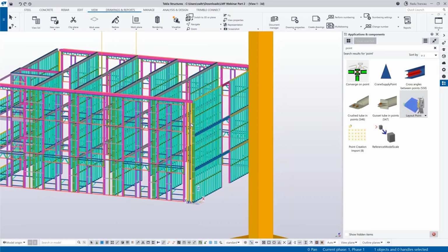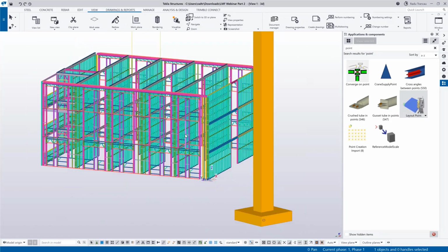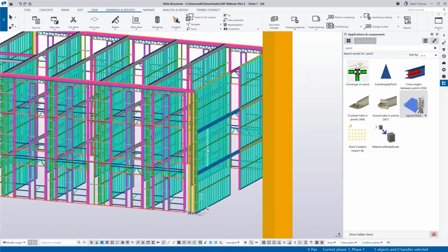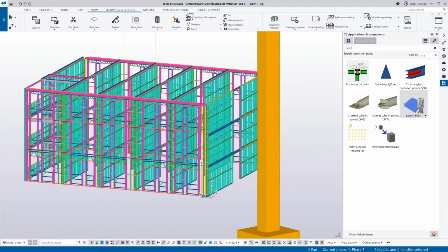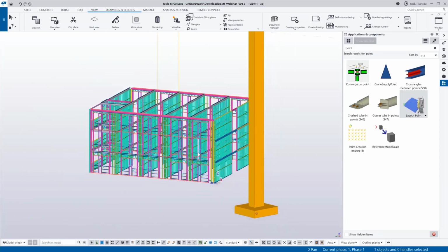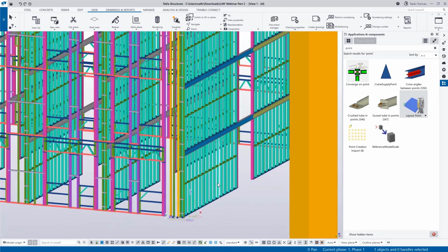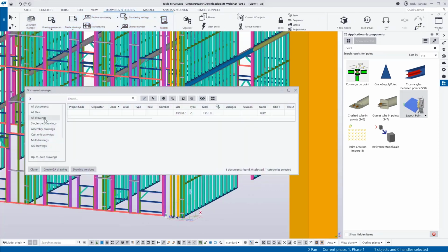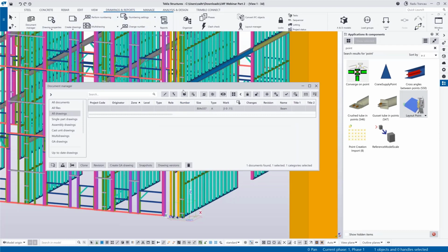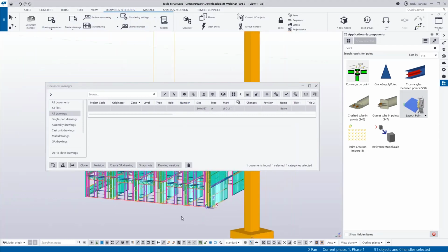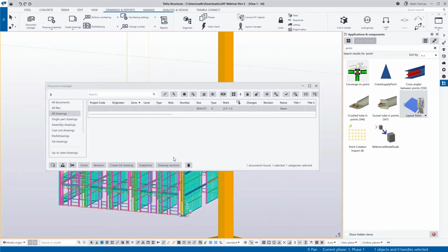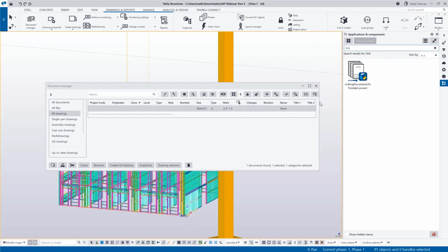Let's move to Trimble Connect to see what we can do with the model. Obviously, Trimble Connect brings together everybody in the team as a collaboration, from the site teams to the architect to the construction engineer. Once you have these panels drawn, you can link your drawings to your IFC. Let's say I've got this drawing made for these typical panels. Just select them in the model. Now you can get this macro from the warehouse as well, called Linking Documents to Trimble Connect.